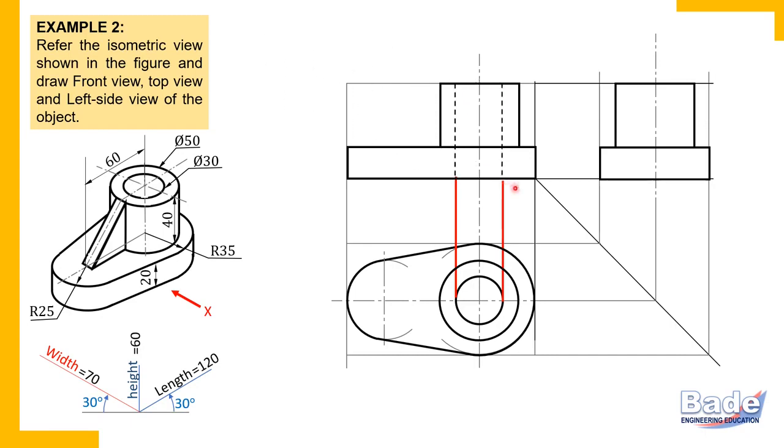Now, very important thing. In the top view it is a circle, so this hole is a rectangle in the front view. Like a cylinder, it is a cylindrical hole. In the top view any cylinder is a circle, and the remaining two views are rectangles. So here also this hole, in the top view it is a circle, so here it is a rectangle. If I ask you, where is this hole in the front view? Don't just show me these two dotted lines. Show me this entire rectangle. Remember, like a cylinder, this is a cylindrical hole in the front view. These are two boundary generators.